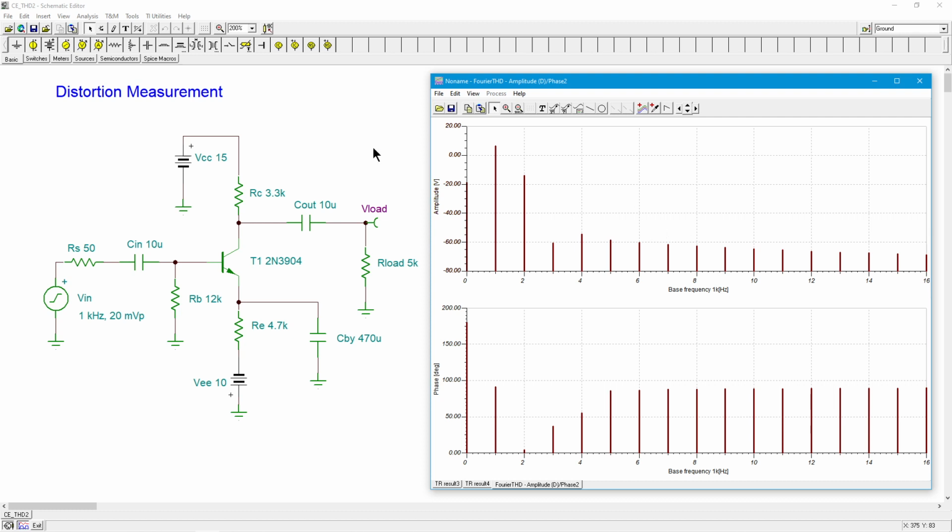All right? Okay. So takeaways from this. First thing is, if you're throwing in a sine wave and you get something other than that nice, pure, pristine sine wave out, you've somehow changed the shape of the waveform in the time domain, then we have added frequency components. We've added harmonics to this. Each one of those things should not be there. We should only have the original signal. And if we sum up all of these extras, we compare it to the original signal, bingo, that's your total harmonic distortion, right? So any warping of that shape indicates there's extra frequency components, right? So any non-sinusoid, this is the other way to say it, any non-sinusoid can be decomposed into a whole bunch of individual frequencies. Okay, you got your fundamental and all these other added things.